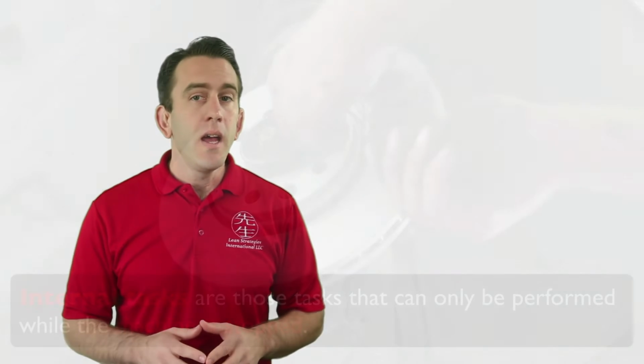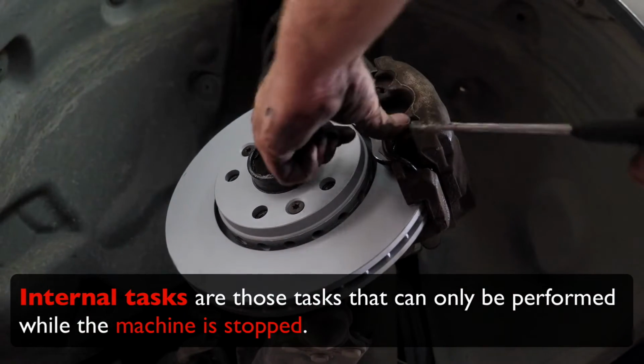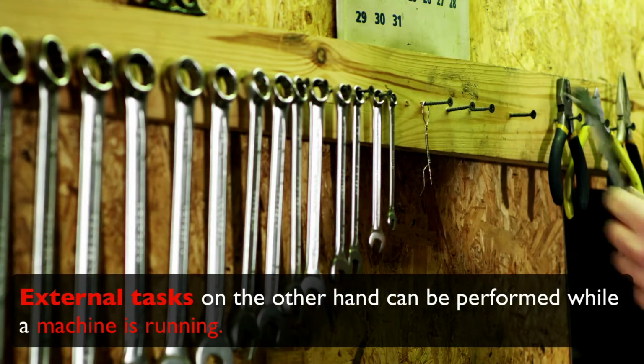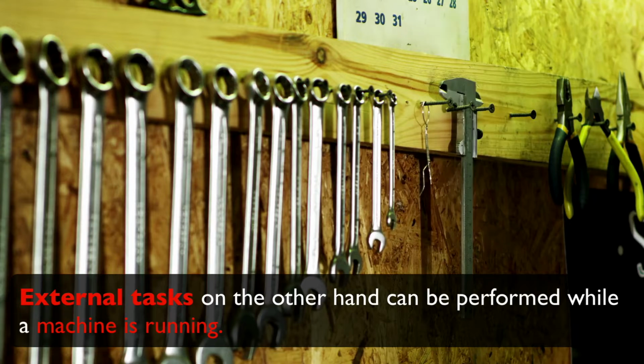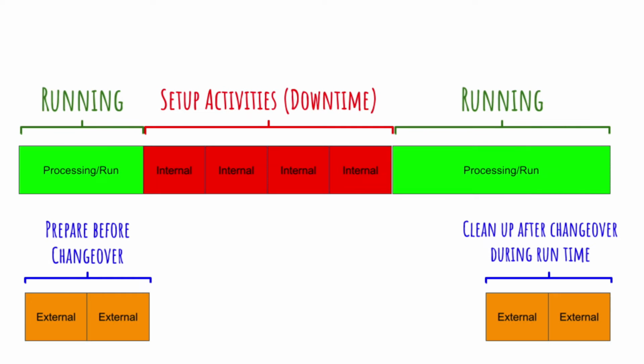As a reminder, internal tasks are those tasks that can only be performed while the machine is stopped. External tasks, on the other hand, can be performed while a machine is running. When we look to differentiate between the two, we are trying to separate work elements or tasks into a group of internal and external tasks. There are many different tasks that can be performed before a machine is stopped. Let's take a look at our IndyCar for a few common examples.